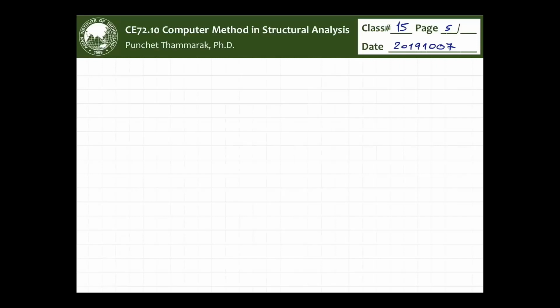Maybe you might show the corresponding KL value, which corresponds to the increment of your P over PE, right? So you can set P over PE and then compute KL. That will be different from the procedure I showed there, where I come up with the KL and then find the corresponding P over PE ratio.